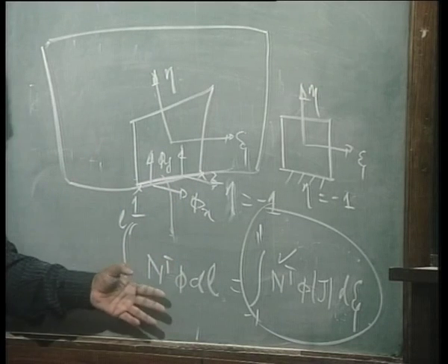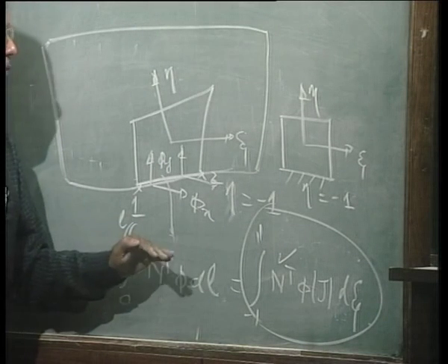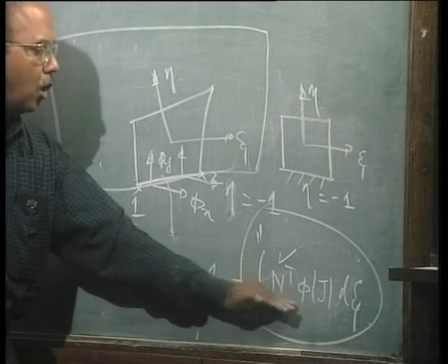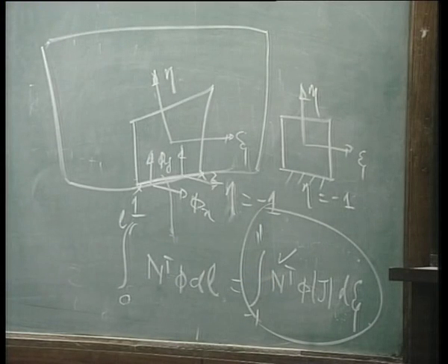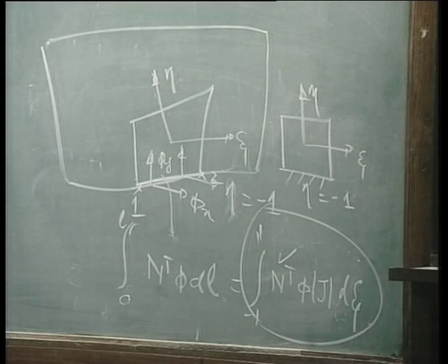How did we get this equation? Please note we got it from our virtual work principle, by transforming it onto the natural coordinate system where psi varies from -1 to +1. So in a nutshell, all the aspects, whether it is the stiffness matrix or the force terms, can be calculated in a very consistent fashion.